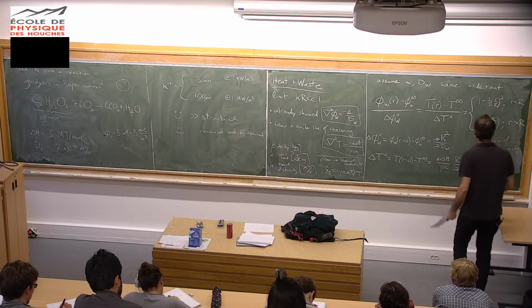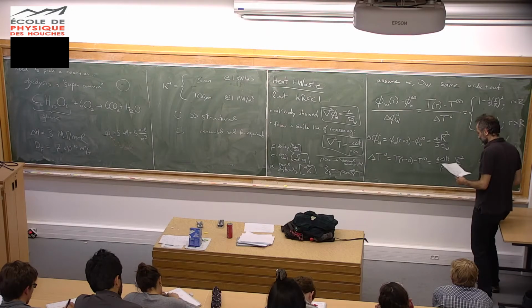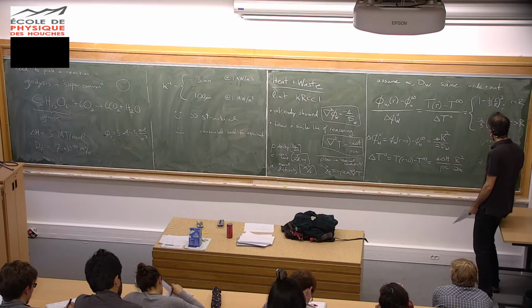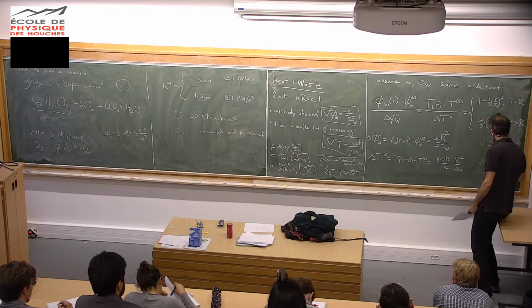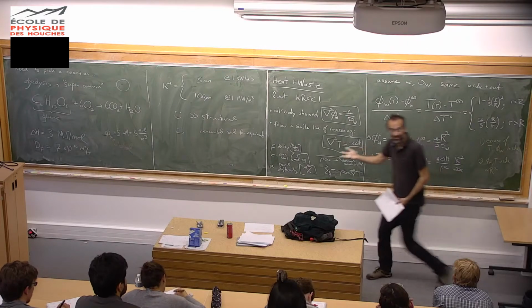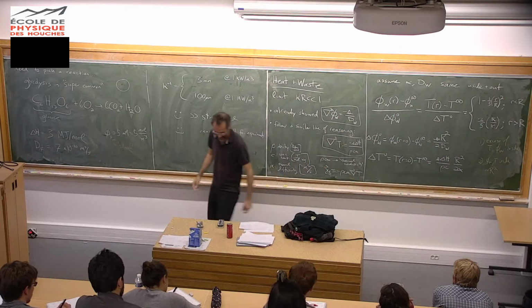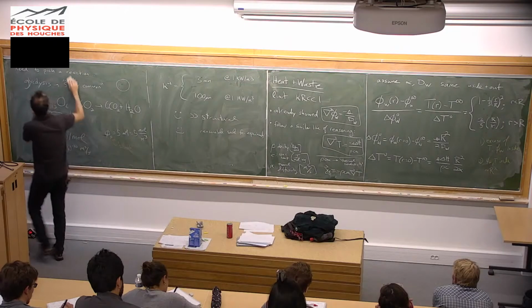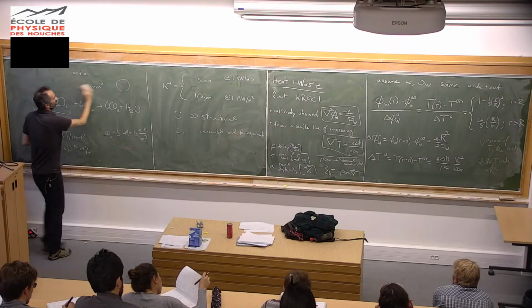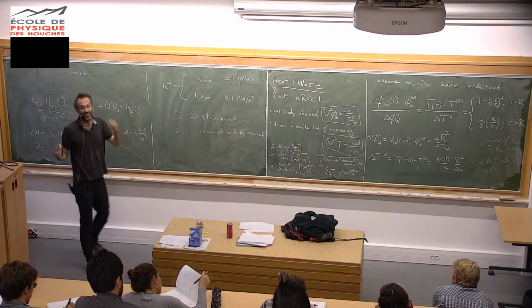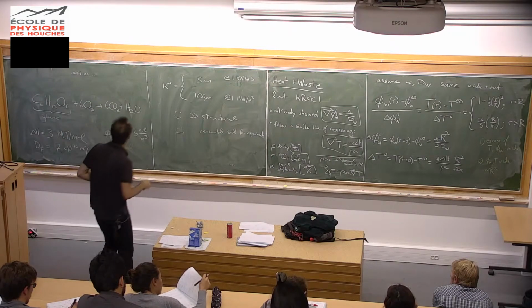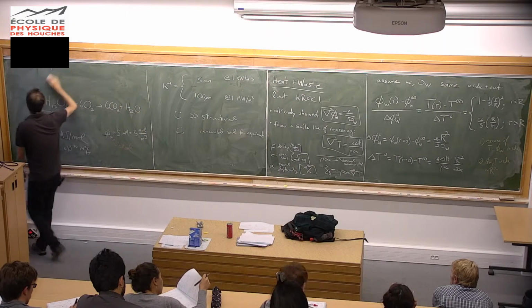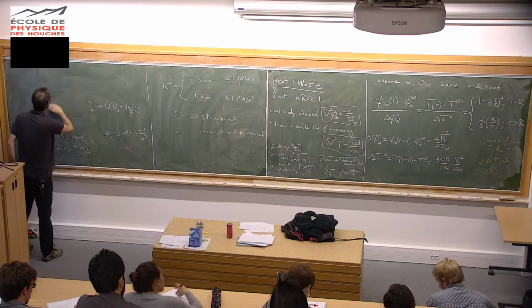The other important thing is that the concentration of waste and temperature inside the droplet scale like R squared. So it's quite sensitive to the size of the droplet. It's not as sensitive as the fuel was, right? The fuel was exponentially sensitive to the size of the droplet. There was a relatively sharp boundary between what was acceptable for fuel and what was not.